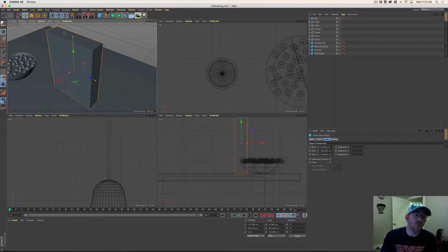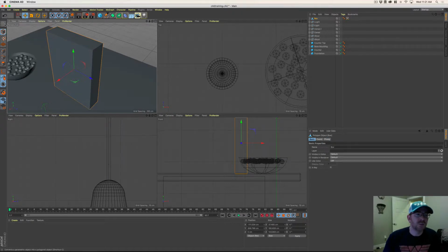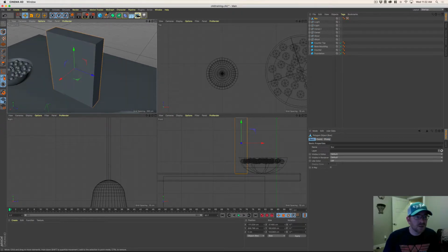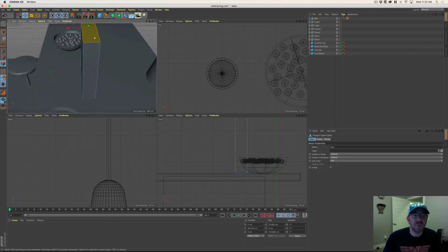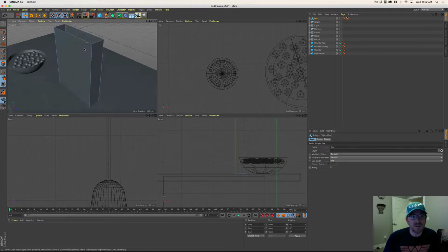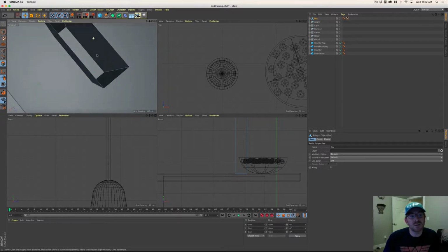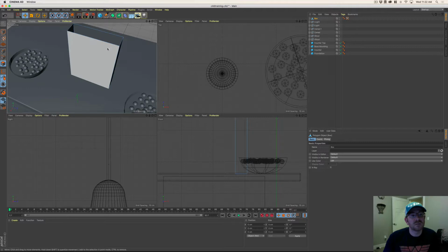First, I want to open this top so you can see through it, and then I'm going to use a plane to create some flaps. So, probably 10 ways to go about this. First, I'm going to turn it into an editable object once I get the size correct. I don't need to add segments, not necessary. Editable object. Next, I'm going to use the polygon tool, and I'm going to click and select this top polygon and just hit delete. Now that box is open. You can kind of take a look inside of it.